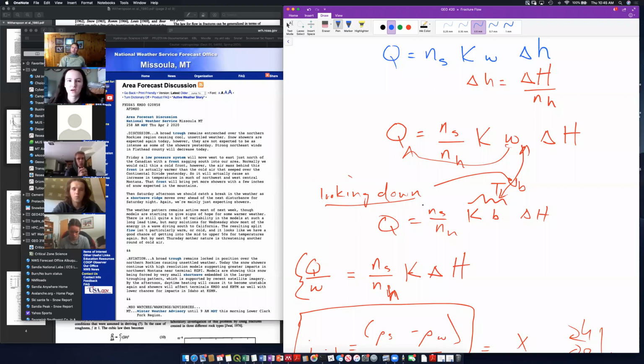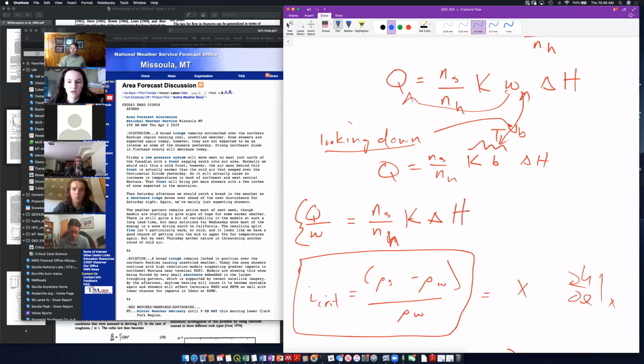All right, so first of all, you calculated from this equation the discharge per unit width of the dam. So if I want to know the total discharge under the dam, it is equal to Q over W, this value that you calculated, times W, the width of the dam. That will give me the total discharge under the dam.